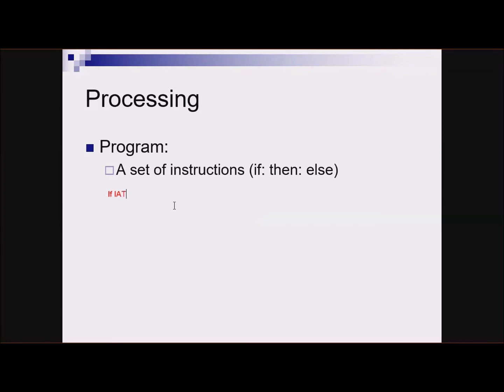If the intake air temperature is less than negative 39, right? Or if the intake air temperature sensor is greater than 247, then turn on the light. Else continue, right? Go on and do something with that reading. So this is just a simple kind of checking different conditions.